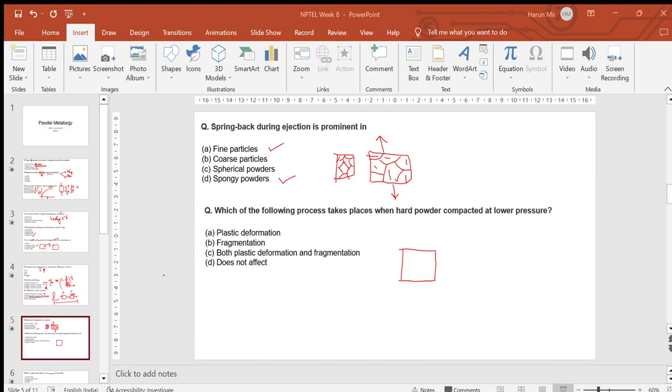Yeah. Now this is an important question. It says that in powder injection molding, feedstock is prepared by mixing 85 volume percent of binder with respect to powder. So they are mixing binder at 85%. You have to say which of the following is the correct statement. The first is that the formulation can form successful feedstock.